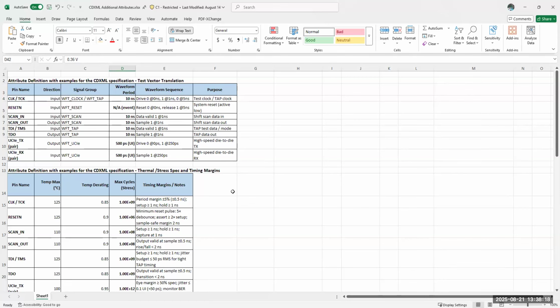See, MBIST patterns have always been easier to port at the top level because they are just configured. The problem was with scan. Scan and boundary scan, now all the tools are supporting it. I took an example where there was a classic scenario where many companies were asking the EDA teams to support the multi-tap structure, because propagating the MBIST controller pins through the IEEE 1500 to the top-level tap was always a bottleneck for the PD teams.